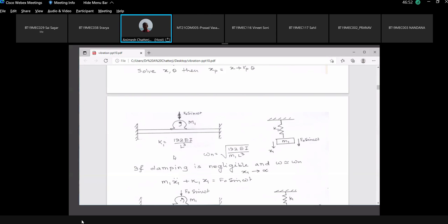Generally slip varies between 2 to 4%. It is not the case that the synchronous speed is 1500 and an induction motor can run at 1400. So this is the reason why, whenever we buy a motor from the market, we cannot ask the motor to run at any speed. Either I have to choose 1500 synchronous speed, or 1000, or 750.